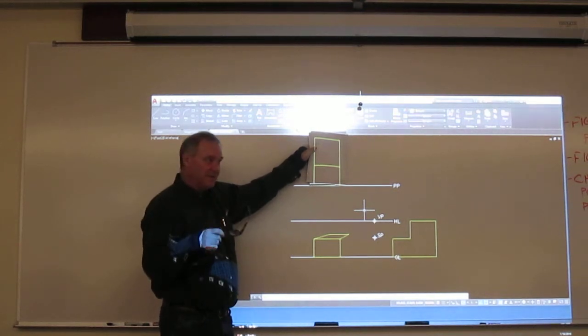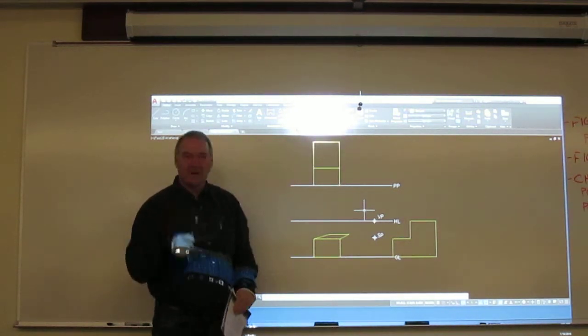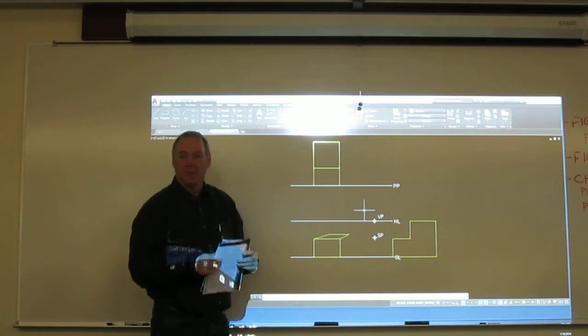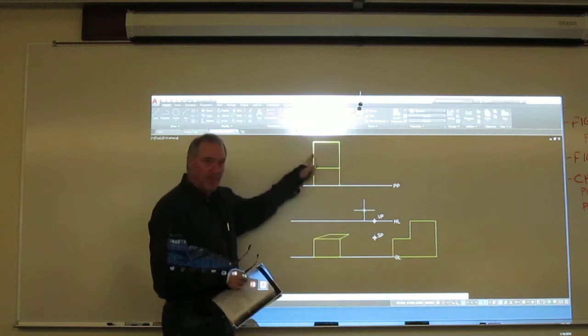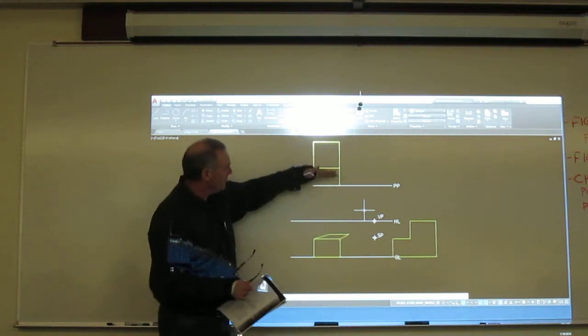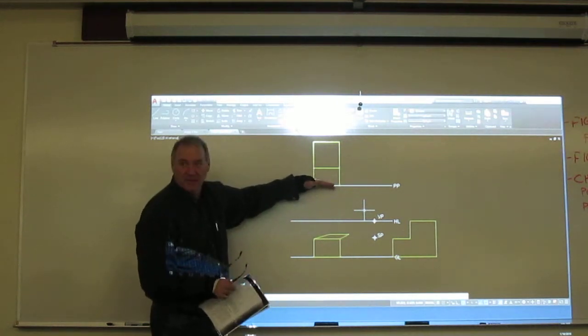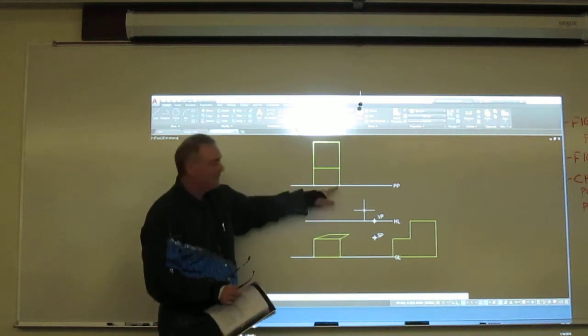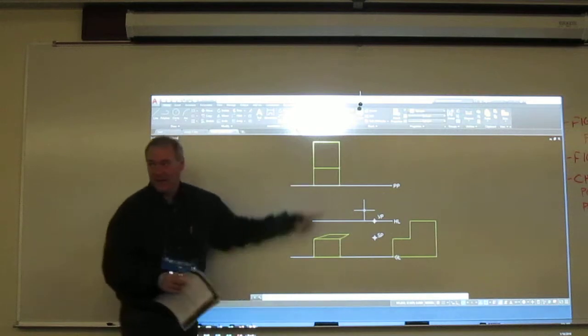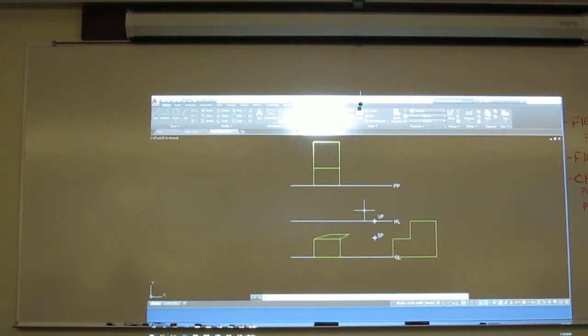When you extend these planes, you have to follow the angle of the plane. Here's the angle. It's vertical. So we're going to take that front edge, move it to right here, find true size, so we know the width of it. Keep in mind, there's an imaginary one right here on the picture plane. When it gets to the picture plane, I can use my right side view.